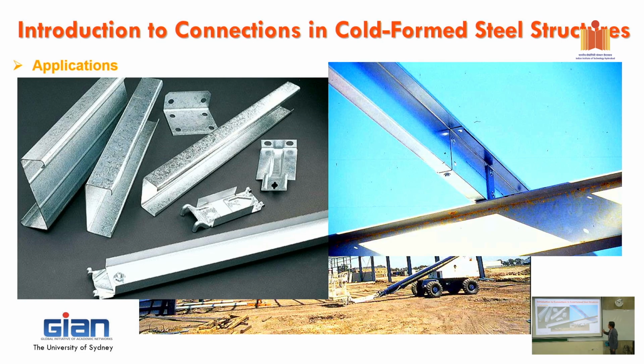And the way we did it in Australia is we bolted one in the flange on the bottom, not on the top, because on the top you're going to put the roof sheeting on. You don't want something blocking it. So just put one in here and one in the upper web. So that is how we do it in Australia. And you can see because the flange, the top and bottom are slightly different, so you can actually stack them on each other, overlap it. So it's how it works.